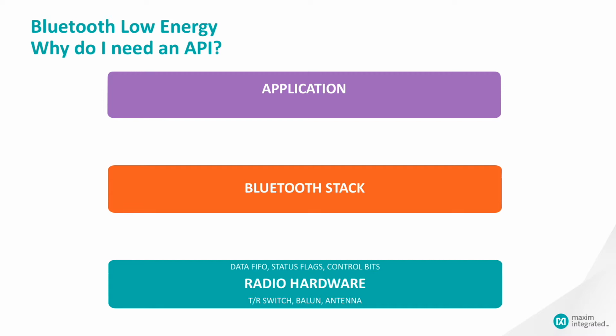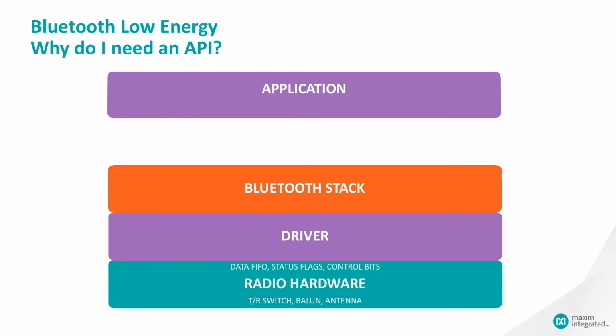But there are a lot of different kinds of radio hardware out there, so do we have to have a different stack for every radio that some chip company dreams up? Well, the answer is no. The chip company writes a driver to connect the stack to the radio hardware. The driver software talks to the various register interfaces exposed by the radio hardware and handles any timing or data flow considerations that are unique to the radio.